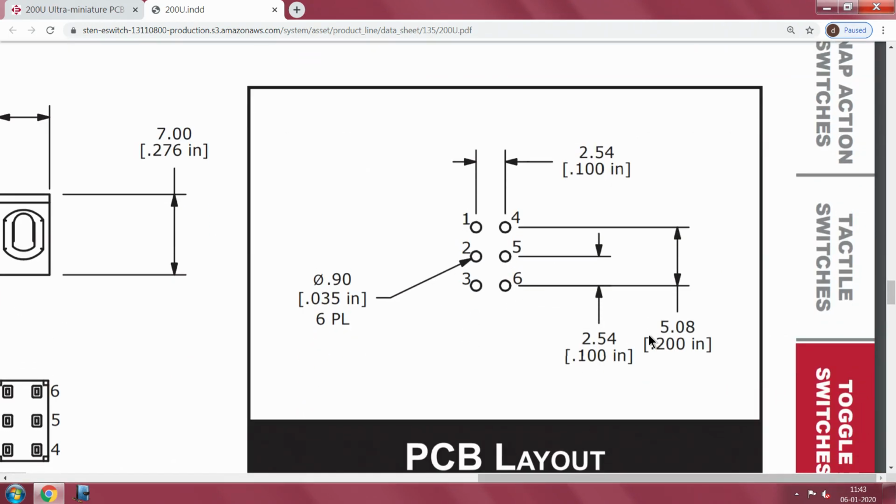So, again with your permission and with your patience, see here something which I talked to you about in my earlier lecture: due to various historical reasons, 0.1 inch pitch, that is 2.54 mm pitch, for the printed wiring boards has become standard, and later on they use the word mils and all that, but I would rather say 0.1 inch and 0.05 inches. So, 1.27 and 2.54 are the standard.